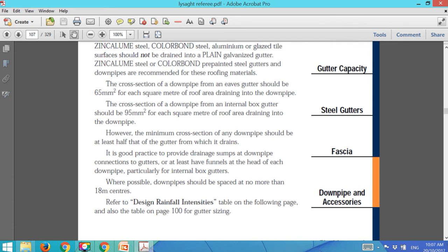When you're designing it from scratch, if you follow these principles, then you should be fine. So basically, if you had a 400 square meter roof, then you can have one downpipe of this size and a gutter of a certain size as well, which you calculate, and conform to this principle, whichever is larger. It's surprising how few you need.